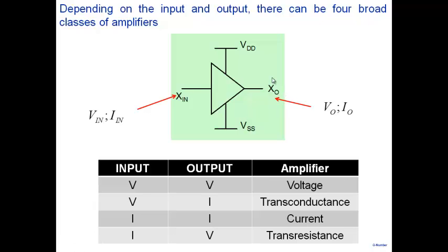Right? So the point that is being illustrated here is that the amplifier is designed in order to maximize this quantity, voltage gain. Okay? Then we call it a voltage amplifier. So our interest is in V0 divided by Vin. So it's designed like that. Of course, at an input and output in general, we'll have both voltages and currents. Okay? Similarly, the amplifier is designed keeping in mind that I'm interested in current as an output here, and voltage as an input here. So it's designed with that in mind.